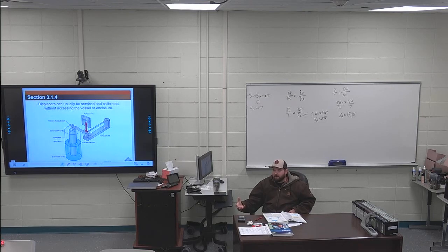So like we talked about thermocouples in the first section, what do thermocouples produce to measure temperature? Current. Two dissimilar metals welded together on the end. Voltage. So they produce a millivolt signal, so that is an indirect measurement because you're taking voltage and turning it into temperature. You're not directly measuring the temperature, you're measuring voltage, but then getting a temperature based on that. Does that make sense? So that is an indirect or inferred type of measurement.